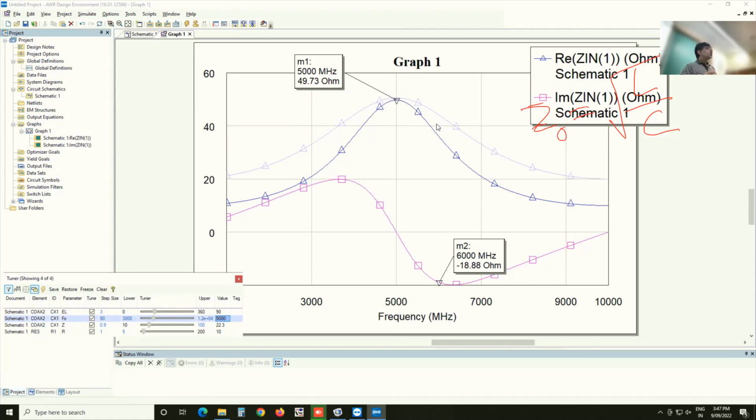And this is also a hint on how you could actually make an impedance transformer. Now, of course, you have to think beyond what we have shown here. How do you make it broader? The clue from here is that you need to match with less mismatch between the two things. But your endpoints are given, 10 ohms, 50 ohms. How can you do it? You do it in steps. So you make first a quarter wave transformer, which will take that 10 ohms to maybe 20 ohms, and then maybe 20 to 30, and then 30 to 40.